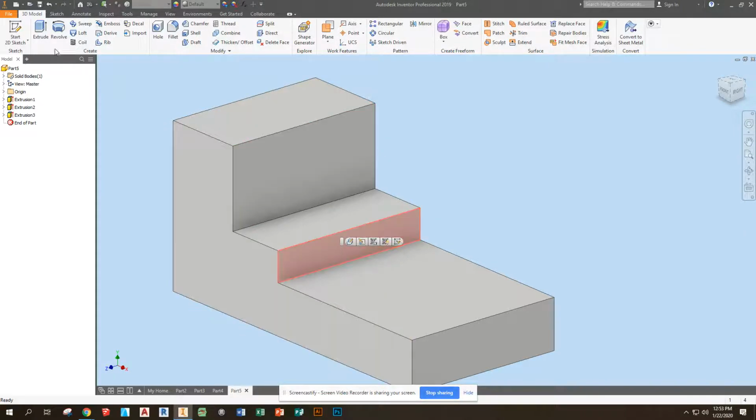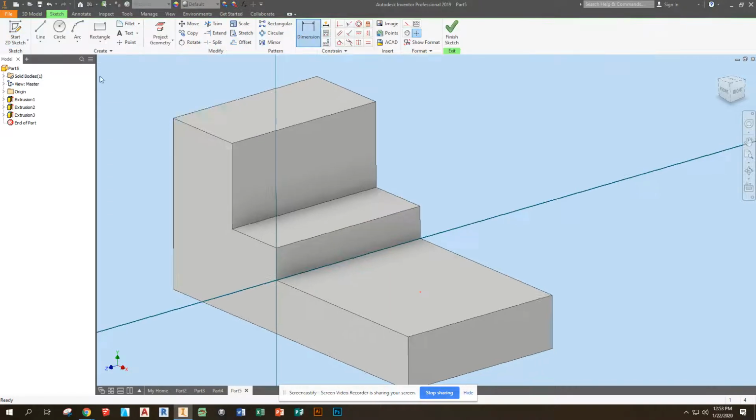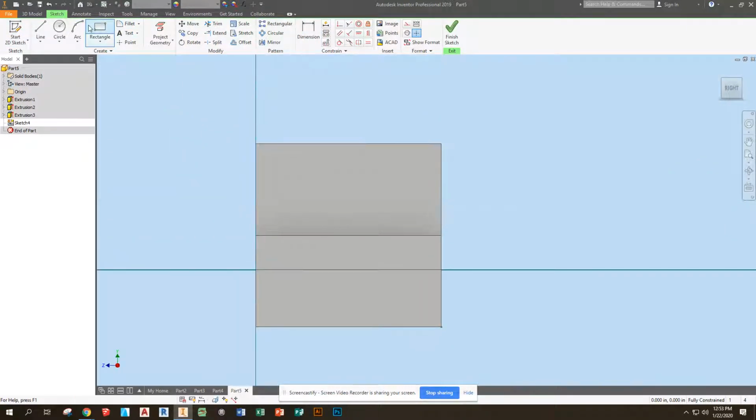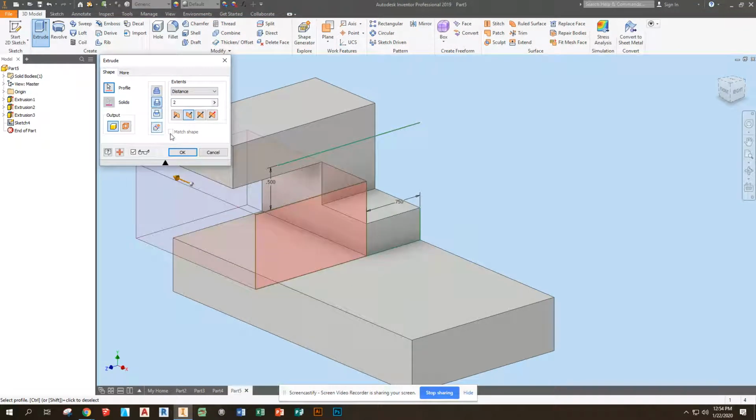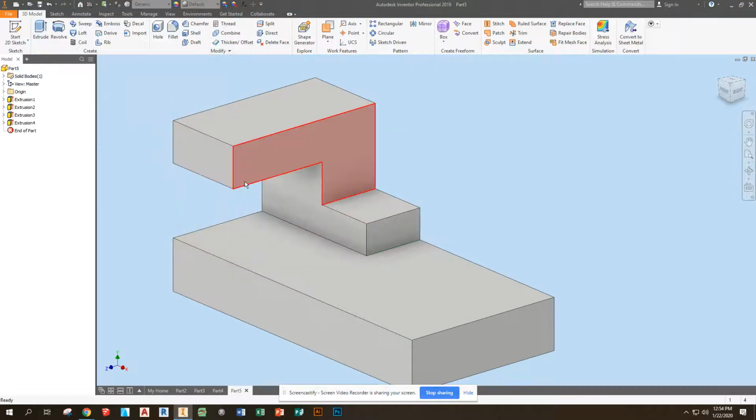So I'm going to take this guy right here, and I'm going to start a sketch there. I'm going to start right down here on this line, and cut it out like so, and leave myself about 1/2 inch right here. This is not going to be quite halfway across, so we'll go 0.75 across that way. Finish the sketch again with my extrude and my cut, so that is going to be a cut. So I end up with this kind of shape going on.